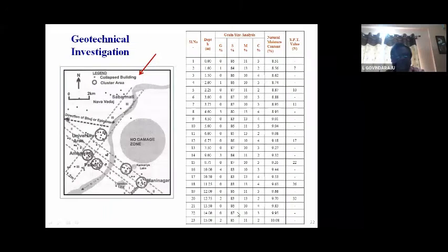Now, this is the geotechnical information data. We collected the geotechnical data by means of a borehole at the particular location where exactly the buildings collapsed. Here you can see we have gone up to 15-meter depth, and the standard penetration test results are shown here.